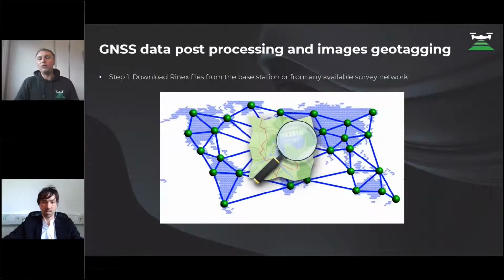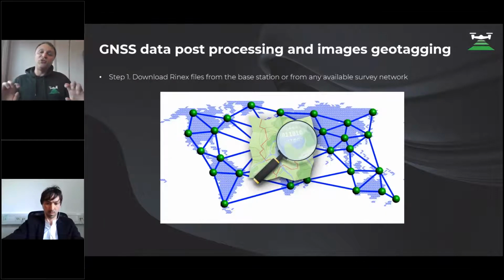And right now we will talk about the data processing workflow. First of all, I would like to show how to make photogrammetric data processing in 3Dsurvey using the Topodrone PPK system, with our software, to achieve accurate results and to minimize your fieldwork, to exclude ground control points from processing and just use one ground control point to calibrate focal lengths, to achieve very good accuracy in altitude. So I will show you.